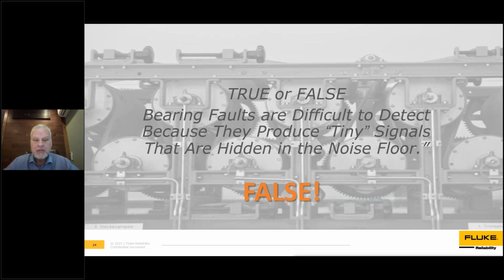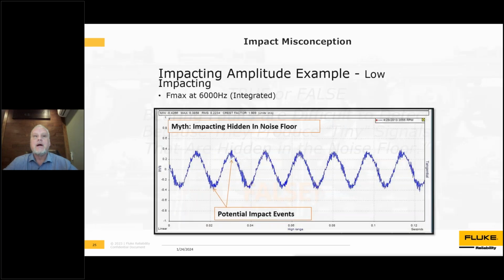And that's, again, a big thing I want to impress upon everybody today. This isn't about some special signal processing method that will bring things out of the noise floor. This is really just about taking a different tack when it comes to understanding Nyquist, understanding that these signals exist. They're coming down the wires from our accelerometers, and our digital data collectors are completely ignoring them. How do we stop that from happening?